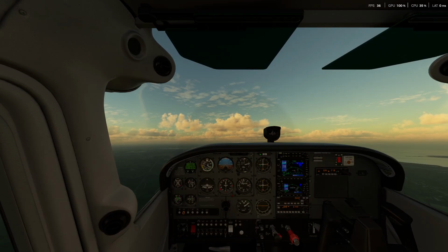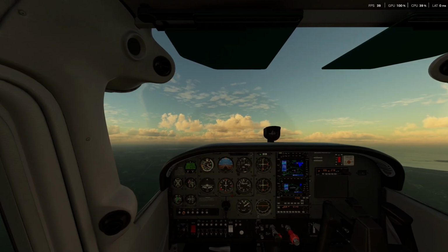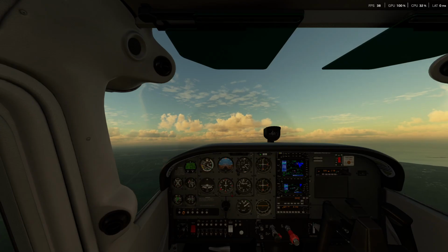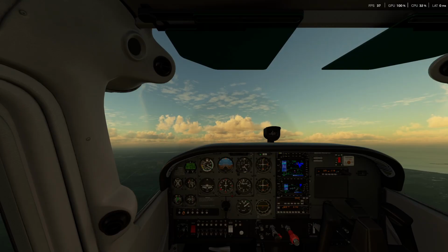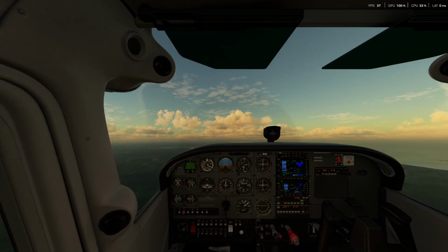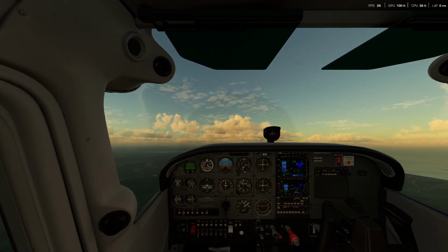So it's a good habit to get into during climbs and turns, but specifically doing climbs. The nose attitude is really high, so you can't actually see out in front of us. So it's good, over 500 feet or so, to just dip the nose down and look out, just make sure there's no aircraft or anything coming straight on.